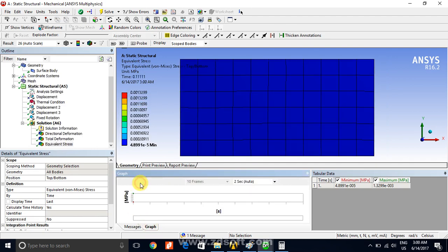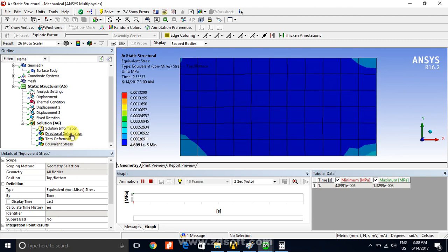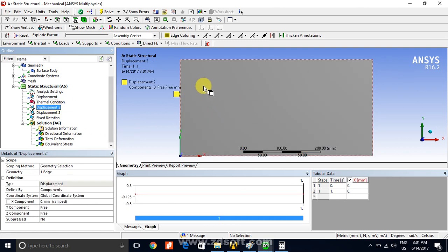This is called a free expansion case. This is all 0. That is what I am telling you, this is the effect of boundary condition, because in case of thermal stress analysis, the stresses will only be induced when it is restricted. So we understand that it is not restricted, it is the free expansion case, and if you do the free expansion case by the previous manner, we cannot do that, we will get some garbage value.